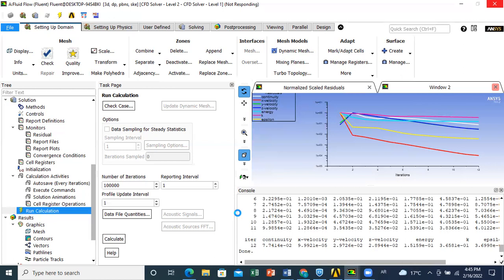Once you see that the features you are using for your CFD models, meaning the methods you are using, the residuals you set, etc., allow the mesh quality you reached, and if they allow you to really predict experimental data, then you say, my model is working well, let me now use it to conduct a parametric study. And then once you have a converged solution, you will see together how you can express your results and how to have physical interpretation of these results.